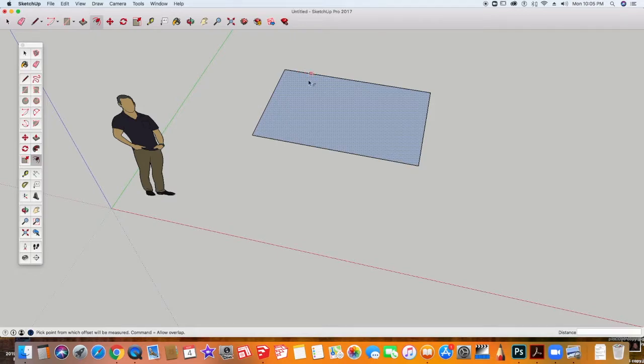So before I start the move, I'm going to make sure that I have that square box, and then I'm going to click, and I'm going to pull out a little bit. And this is going to give me the walls of my room. The walls of our room for this particular project, we're going to use 5 inches. Because presumably this is an interior wall, and exterior walls sometimes can be 6 inches or even a foot, depending on the type of material you use.